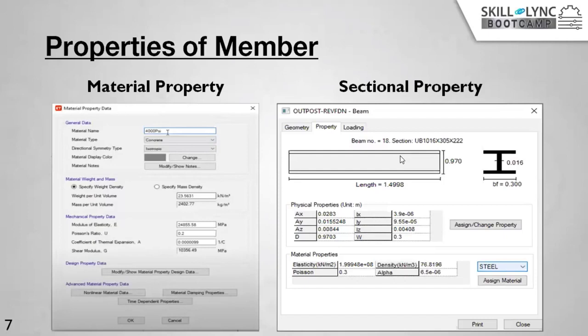There are 1,000 beams in the floor of a structure, and you are giving 100 types. Among those 100 types, some 50 types of beams have very little weight difference from the others. It means you have to combine those beams into a single property, which will reduce the fabrication cost.